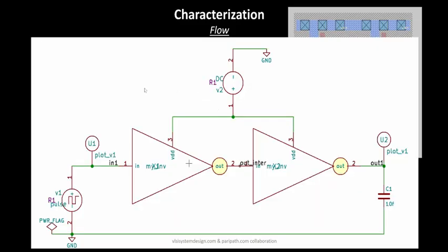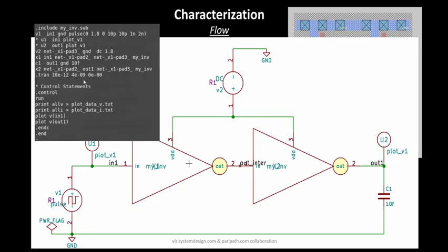You have the description of the buffer. For example, 2 inverters connected back to back, you have the description of the entire buffer along with the power sources and everything that is getting connected. Okay, so you have this description as well. You have the spice extracted netlist. Whatever you see in this layout, you have these metal layers, these contacts and everything. Each and every element will have associated resistance and capacitances with them.